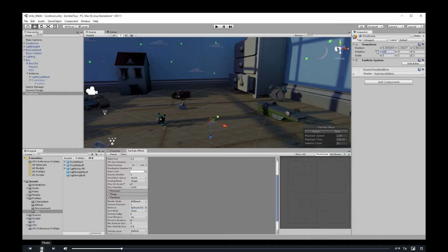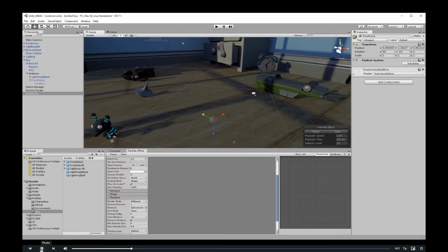I'm going to give this a rotation of 90 about the x-axis, but I'm also going to give it a rotation of negative 60 about the y-axis. The reason for the negative 60 degree rotation about the y-axis is because I'm going to want the cone to project between the y and x axes. So if we look at the y and x axes, currently being the axes that point left and right on the screen, we want the cone to emit right between those.